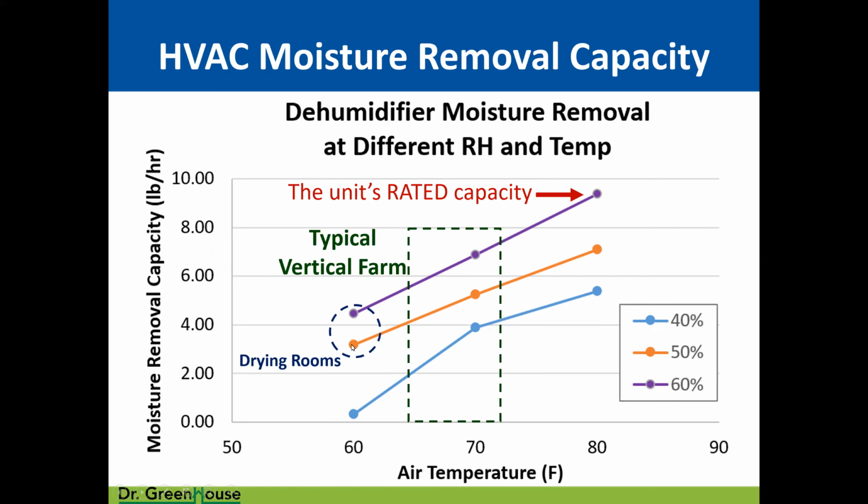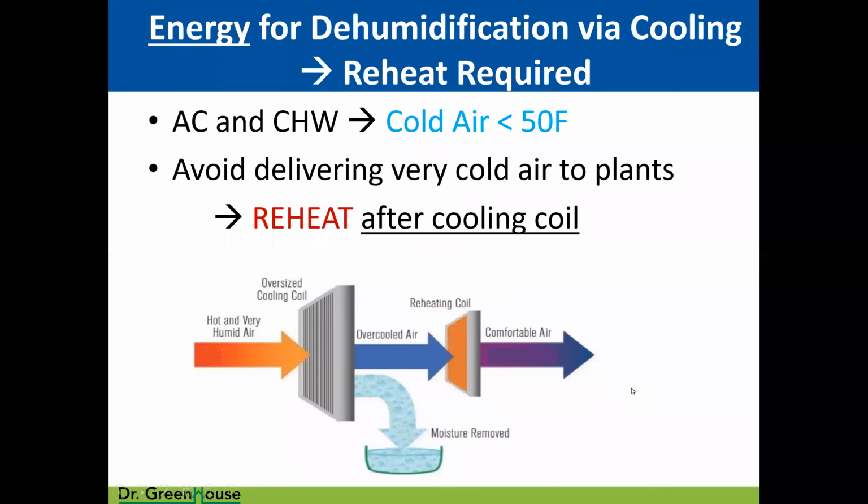Yeah. And that's why a lot of you are having trouble with humidity control, even with dehumidification equipment dedicated to your facility, because you are assuming, and nobody told you otherwise, that what the equipment says it's going to do on the product sheet is what it's going to do, when in fact it's going to do half or a quarter of that rated capacity. And so you actually needed more of their equipment.